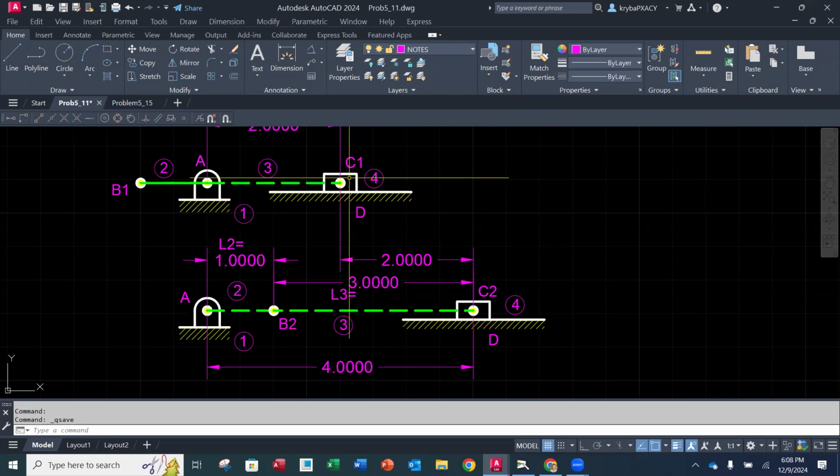So this is what we're calling C1, okay? And if we go straight down here, then as we extend our crank in line with the connecting rod, the furthest out position is going to be C2. So if we look at the dimension between C1 and C2, that is our 2-inch stroke. Do you see that? Okay.